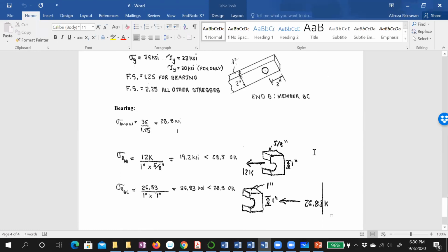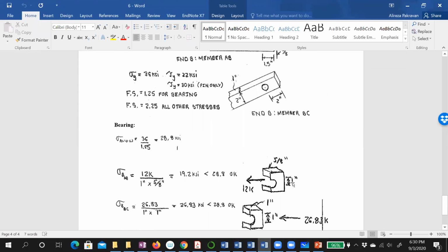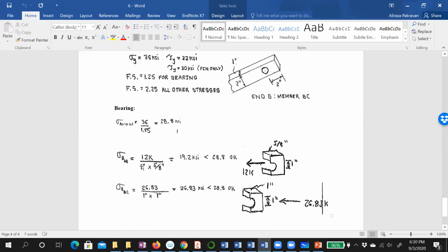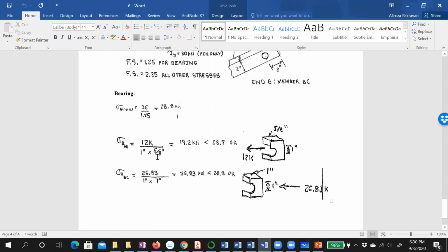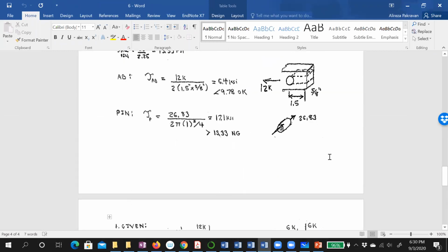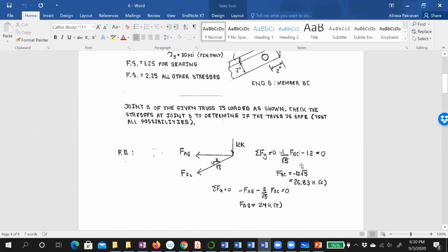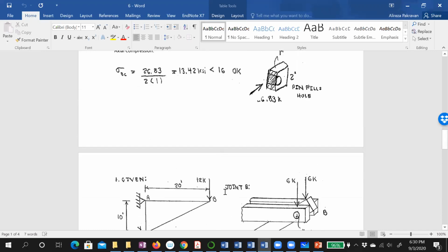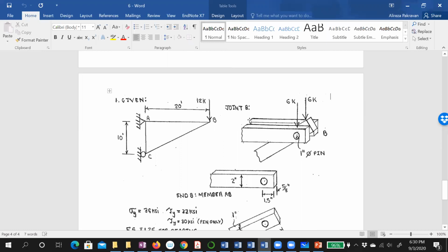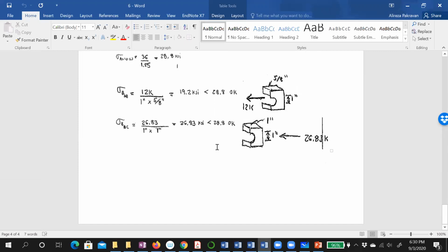Professor, quick question. Yes, sure. So we don't have to assume two members for the tension. We can just do one. Yes, we can assume two, but if you do, you should use the 24 in the numerator and multiply the denominator by 2, because we have two sections. For simplicity, I just focus on one of them, but you can use 2. Since there are two members, you could do each one, because these two members get the same force. Okay. Yeah, right.